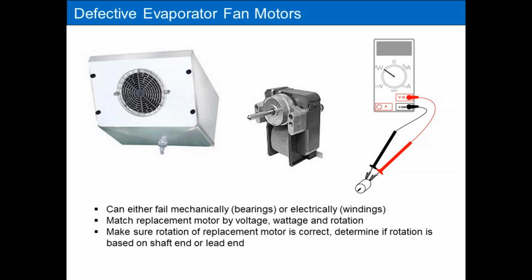Verify it, make sure you have voltage going to the fan first, and then if you have voltage going to the fan and it's not spinning, change the fan. So that's a pretty simple tell.